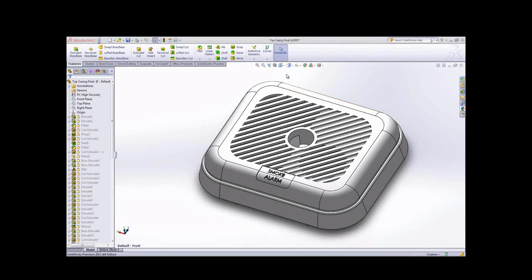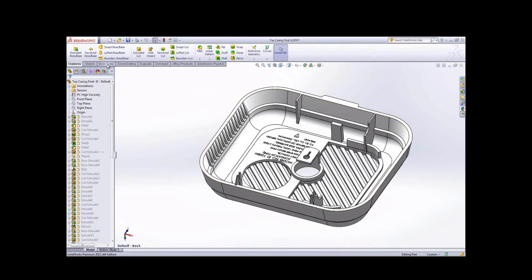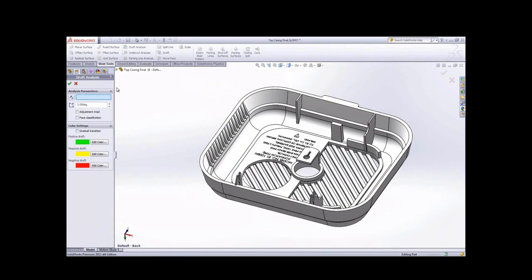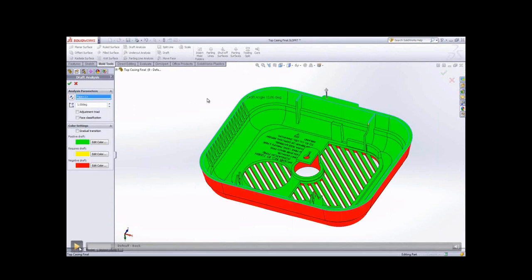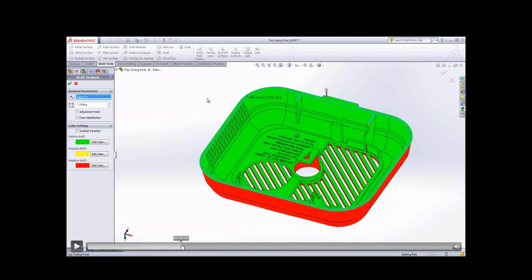The first thing you might want to do inside of SolidWorks is analyze this model for draft analysis. The draft is very important, and injection molding plastic parts require a draft in order to be injected properly out of the mold cavity. So in the early stage of the demonstrations, it's more focused on the mold features that we have in SolidWorks. For example, like draft angle, putting in web to support it. So I'm going to skip the front portion to save our time because we have limited sharing time for today.